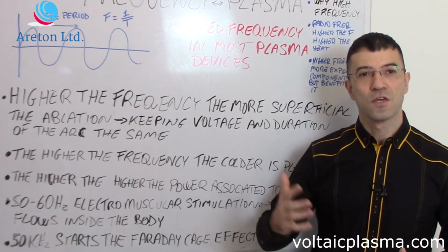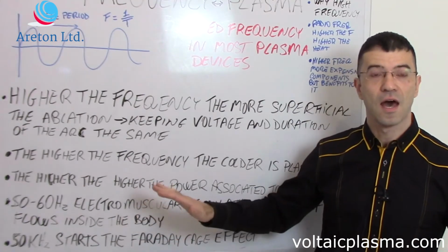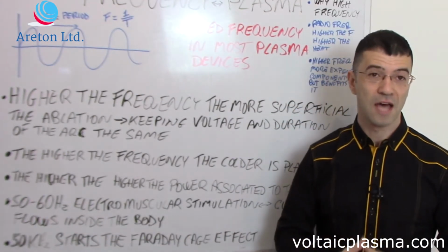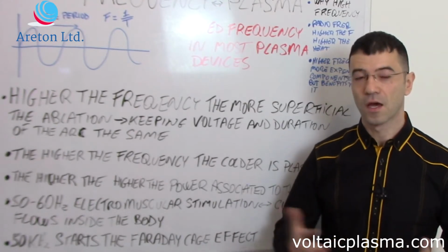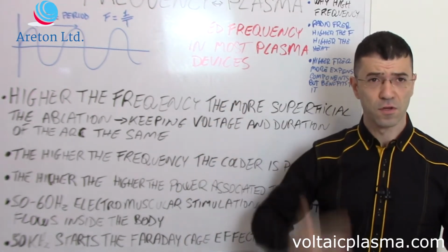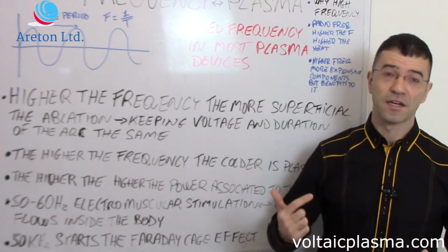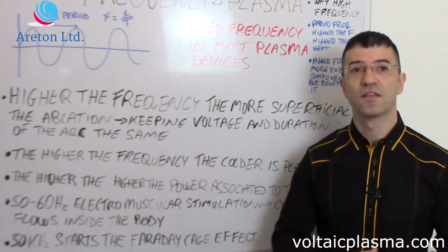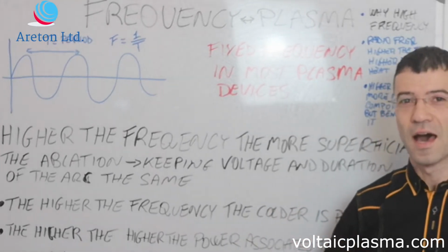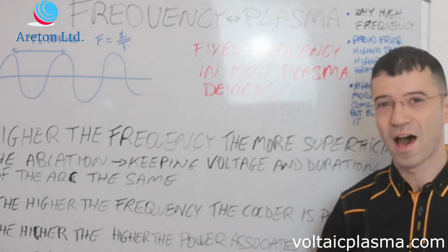So what happens is you can actually die of heat up of the internal organs if you touch voltages at these frequencies which are in the region of kilovolts. And if you touch those without any protection, and the current goes through your body from the mains into earth, then you could potentially die not of cardiac arrest, but mainly from the heat that develops inside your body, because the current passes through your internal organs, and therefore it causes a lot of damage that way mainly.